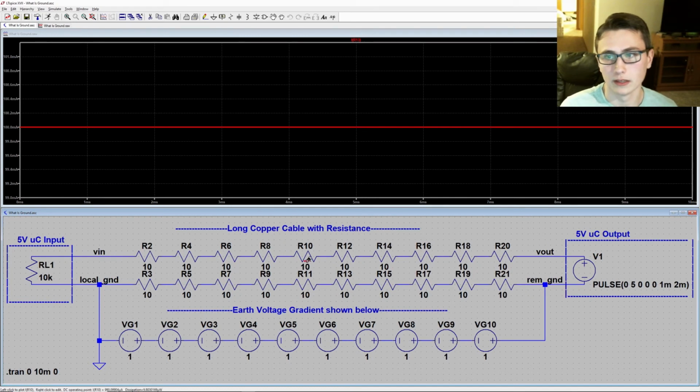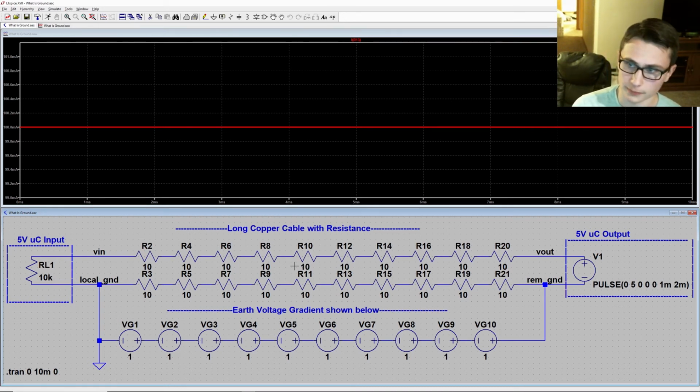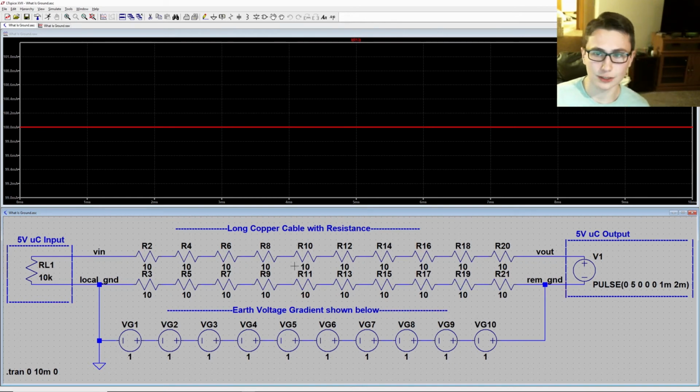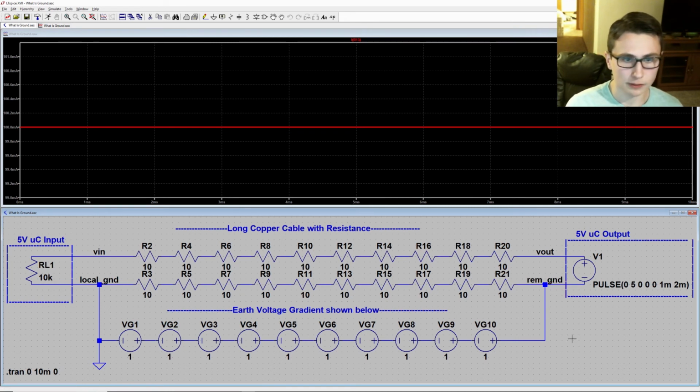Of course, the reason for this current and voltage shift is made obvious when we can see the voltage potential underneath the ground, or underneath the Earth's surface. But it isn't always practical to measure the difference in ground potential between 2 points that are miles apart. That's ultimately what causes issues in systems that are separated by distance when they don't have proper considerations for the potential difference in ground between 2 points, and demonstrates the point of why we all universally decided to use ground as our reference voltage.